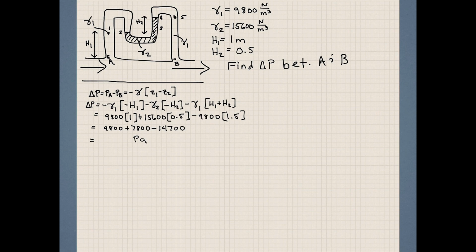The reason I picked that up was because I knew that the pressure that's pushing the fluid through this pipe should be higher at point A than at point B. So the pressure difference between these two is 2,900 pascals. We can use that for several things. If we put a flow obstruction here, we can use that pressure difference to calculate what the flow rate is between these 2 points.